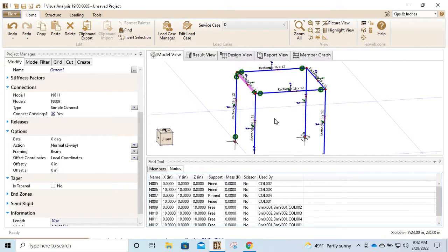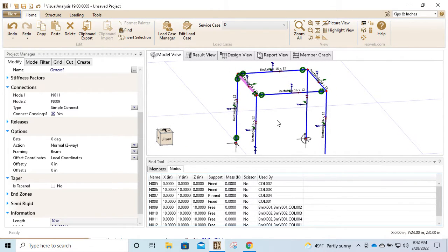That's more intuitive than thinking. It's hard to think of something that would induce a node to spin, like a load that would cause one node to not spin. It's necessarily inducing it to spin, it's an instability, right? Yeah. It's not restrained. And so then it ends up screwing up the stiffness matrix, making it singular. You can't take the inverse of it, and then something goes awry.